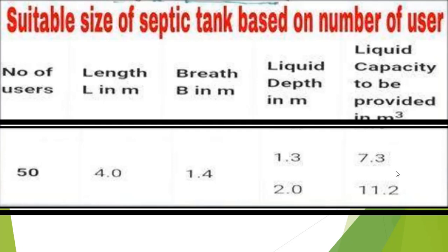In an earlier video, I have explained what is meant by M20 and M15, what is meant by M and what is meant by that value. Third, the outside and inside faces of the wall and top floor of the septic tank should be plastered with a thickness greater than 12 mm of 1:3 or 1:4 grade mortar. The concrete should be prepared waterproof and all the inside corners of the septic tank should be rounded, giving slope towards the center.